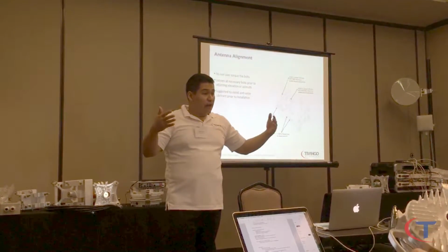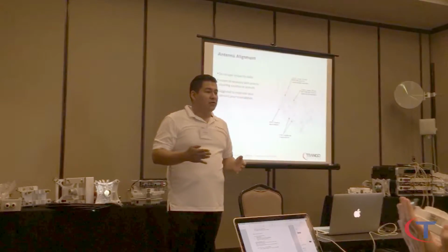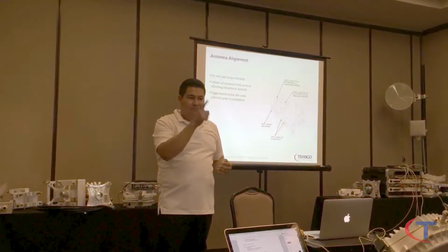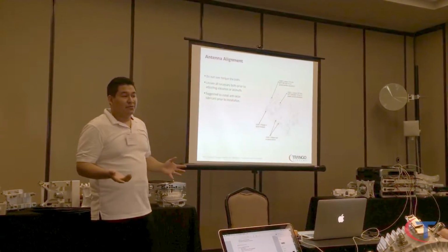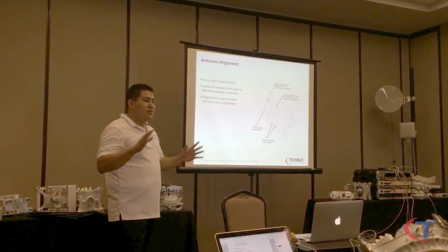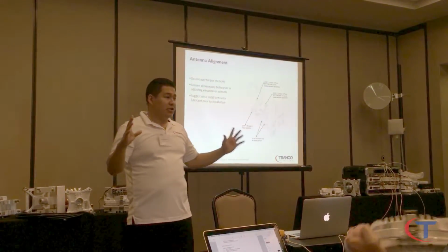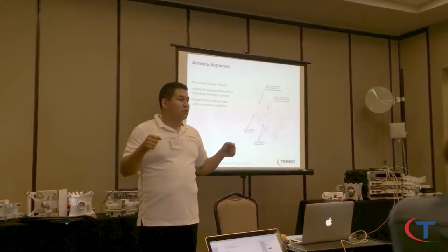If it moves around, you're going to see your RSSI do what? Symmetrically go up and down. Exactly. So, and it happens, right? So just make sure if it's a 4-footer, 6-footer dish, you have the right struts on the tower.